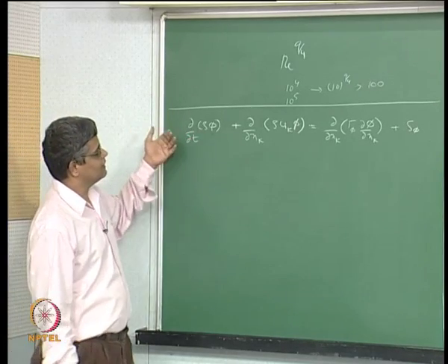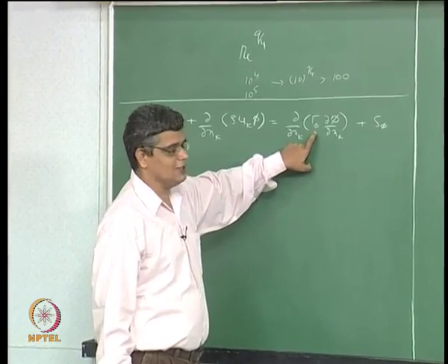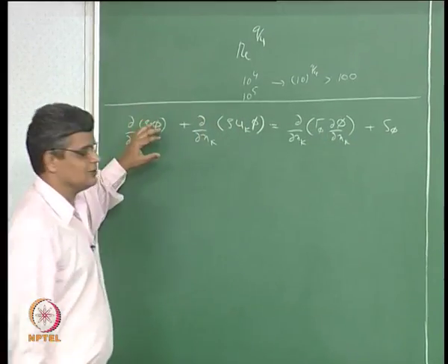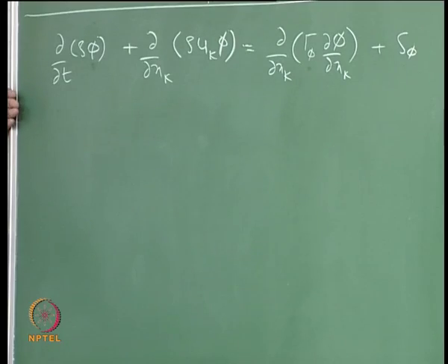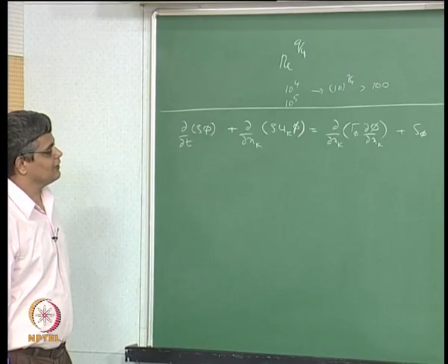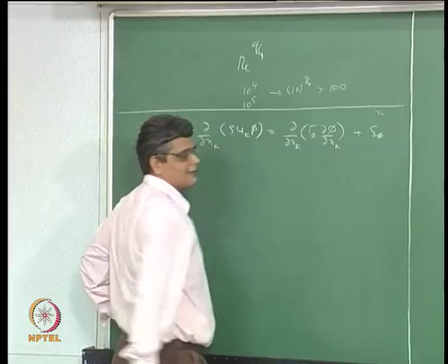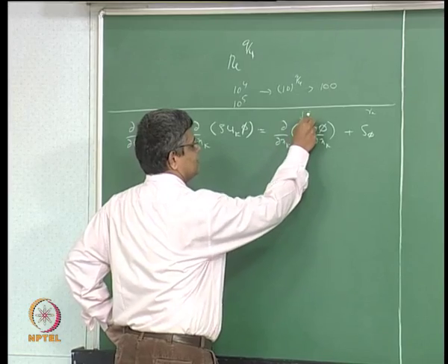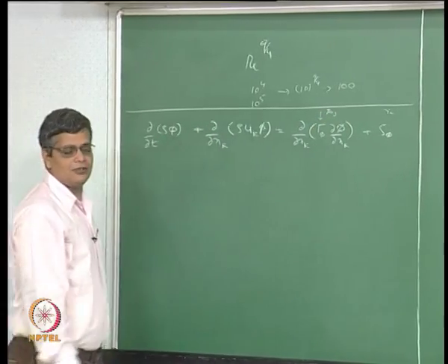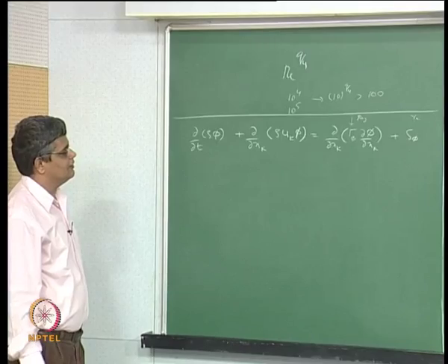the continuity equation. By substituting different expressions for the effective diffusivity and the source term, we can make use of this equation to represent the continuity equation, the momentum equations, the energy equation, and the reacting flow equations for the species conservation equation. We note that in a species conservation equation the source term is the rate of generation Ri, and this is that diffusivity Dij, which we have said is a fairly complicated thing for a multi-component diffusion to be done exactly.